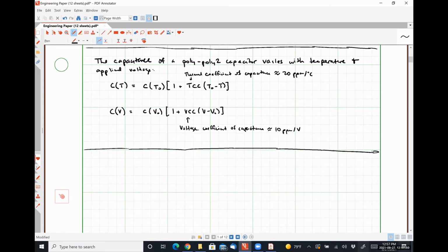Any thoughts? We can't move our metal one layer any further away from our bottom plate, right? So if we wanted to make a large capacitor that didn't have as large of a parasitic capacitance, we could make it between metal layers 2 and 3. That's a fairly obvious solution, right?